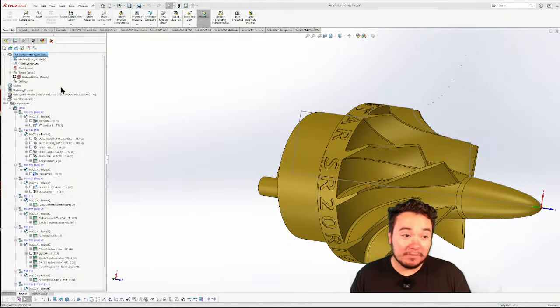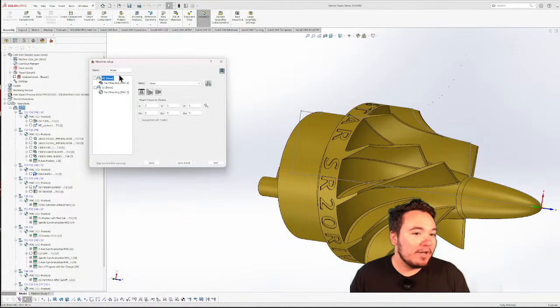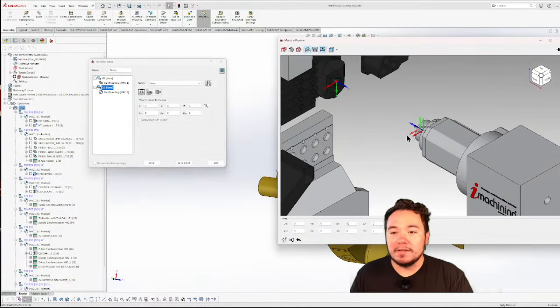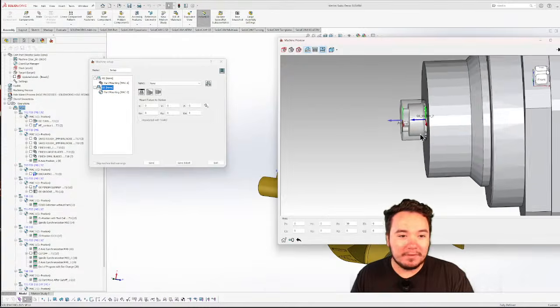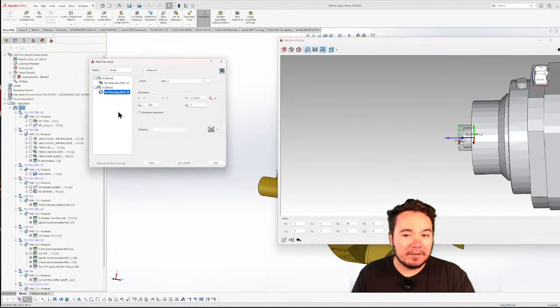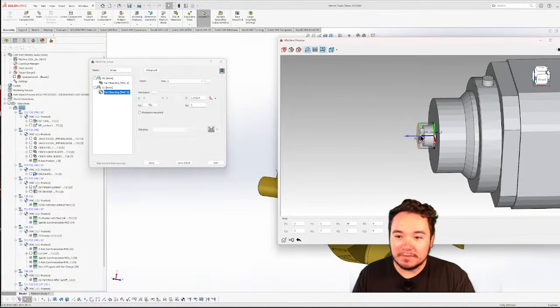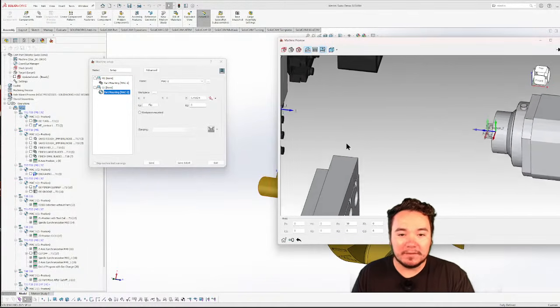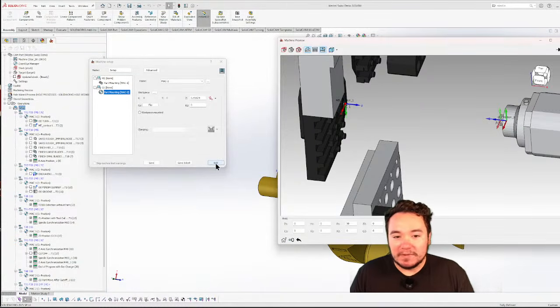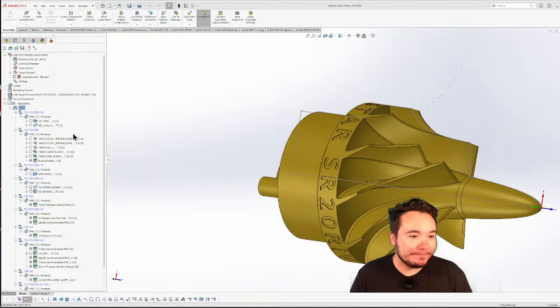So now we're pretty much ready to go ahead and start. The only thing I do like to double check is coming to our sub-spindle here and making sure that it's mounted where I wanted to pick it up. And for right here, you can see it's off of Mach 2. It's 40 thousandths from the face. Once that's set, you're pretty much ready to go. Make sure that you're selecting what Mach position you're going from. And then, yeah, pretty much basic stuff.